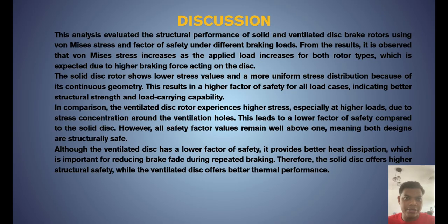This results in a higher factor of safety for all load cases, indicating better structural strength and load carrying capability. In comparison, the ventilated disc rotor experiences higher stress, especially at higher loads, due to stress concentration around the ventilation holes. This leads to a lower factor of safety compared to the solid disc. However, all safety factor values remain well above 1, meaning both designs are structurally safe.